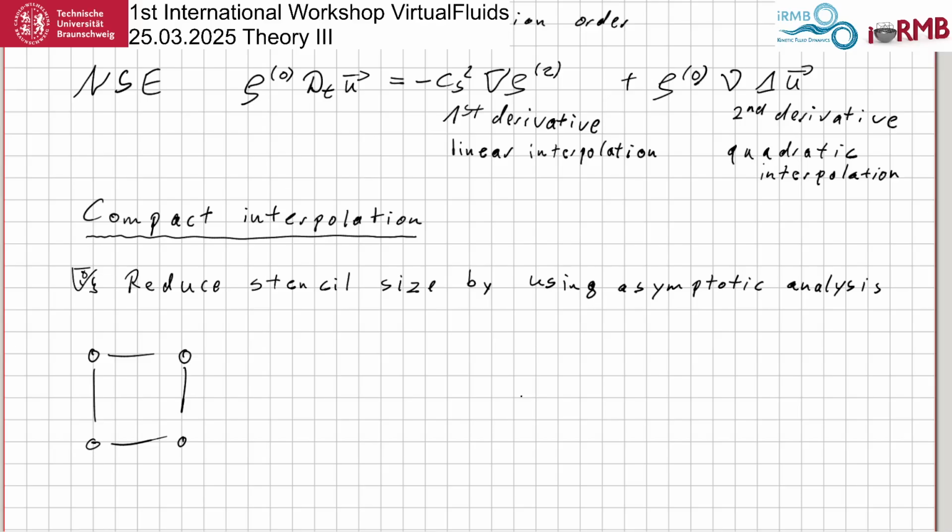This is now going to be important because in VirtualFluids we talk about interpolation cells, and they are different from the cells in waLBerla, where a cell is the surrounding around one lattice node. In VirtualFluids, a cell is the inner part of this box where we have the nodes on the vertices.